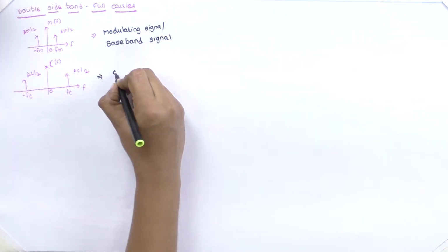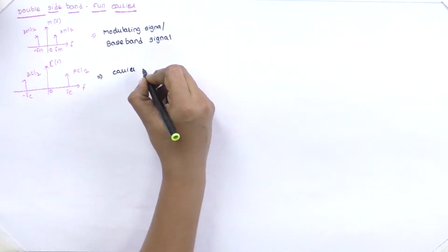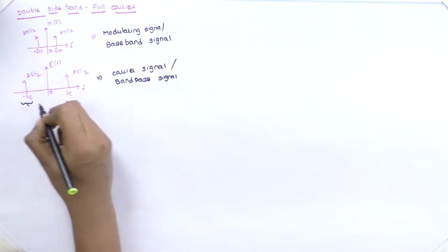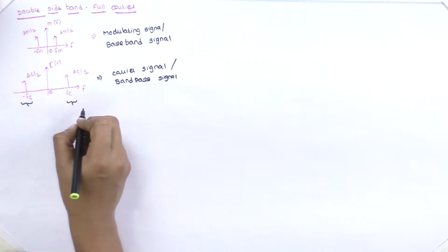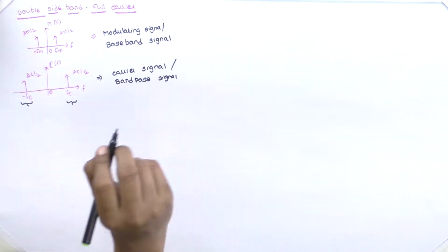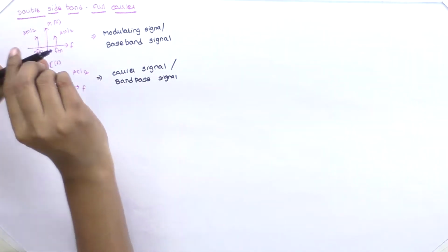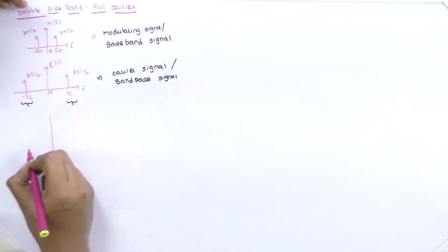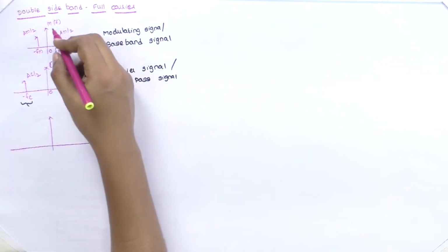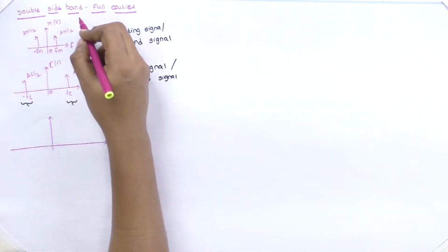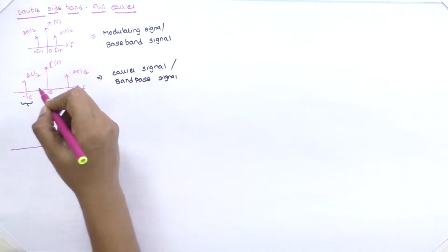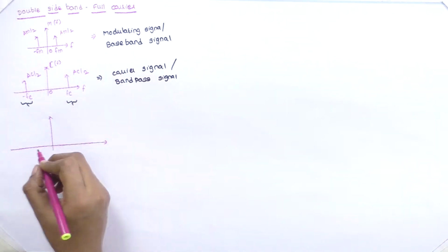Our carrier signal is referred to as band pass signal, since we have frequency only in a particular band of frequency slot. So after modulation, according to the amplitude of the low frequency signal, the instantaneous value of amplitude in the carrier signal varies.